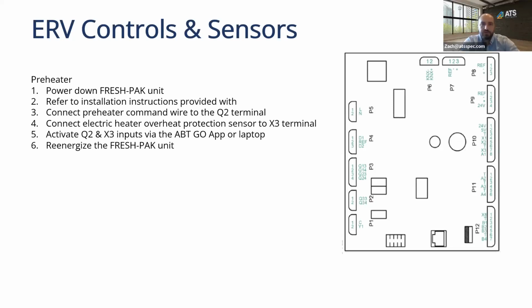Perfect. And then there's the CFM range. I believe it's factory set at 50 CFM, and then it goes up to around 150, maybe 165 or so CFM on the top end when you're going into that full boost mode, for say like the bathroom exhaust. But there's different levels: there's comfort, and there's occupied, and there's economy. So there's different levels that it can be set to and programmed to.